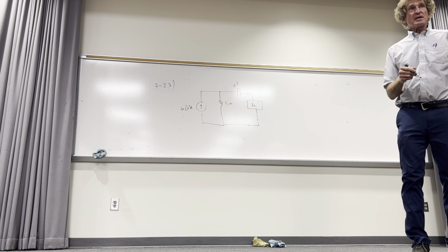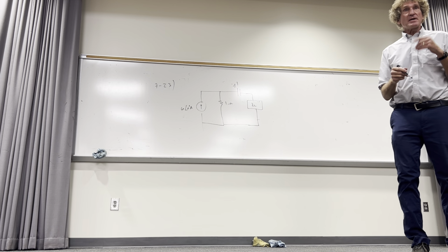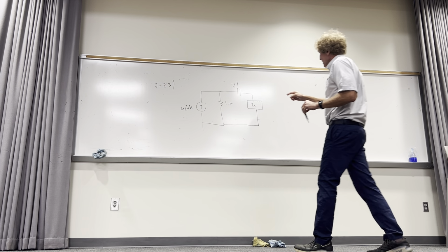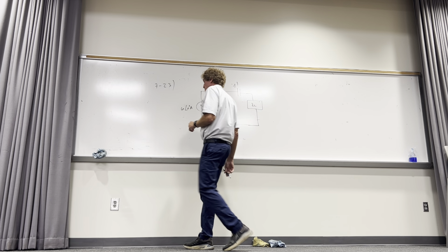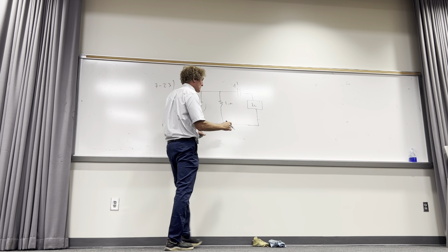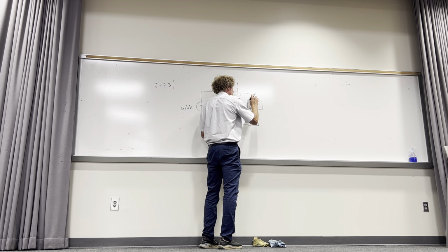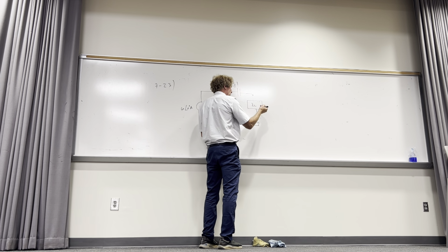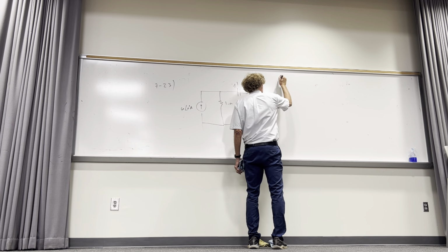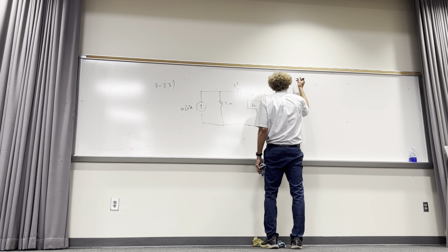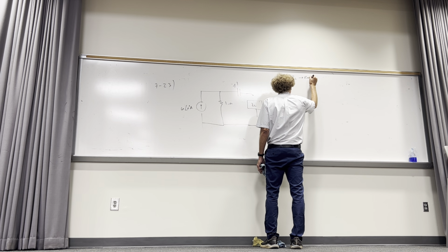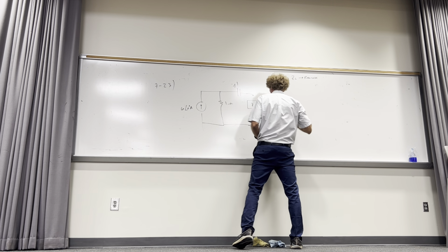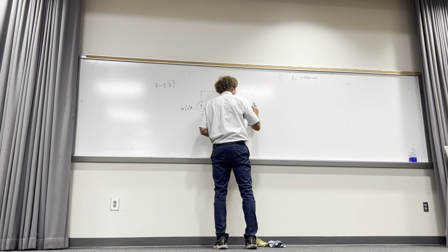So the first thing you have to do is create a Thevenin equivalent circuit of everything on this side. So I'm going to do this, make sure you see what I'm doing. Here's the load right here. I'll just call this, here's where my load is, right? So the first step with Thevenin is always remove the load. So my load, ZL, is removed.